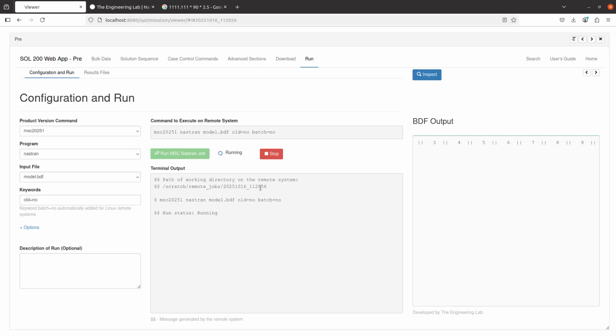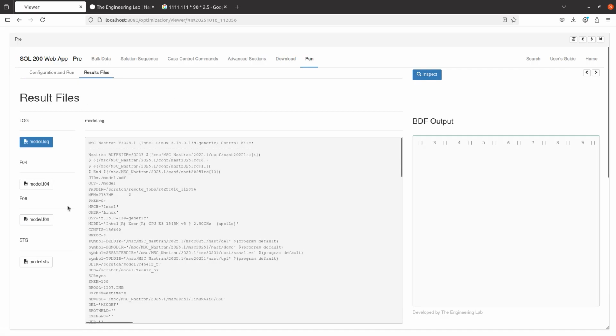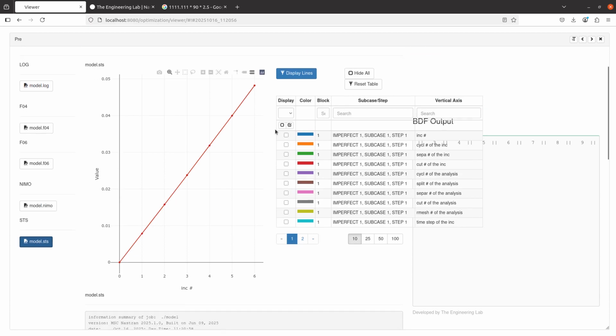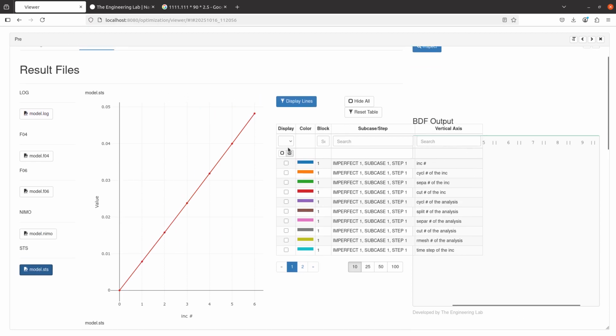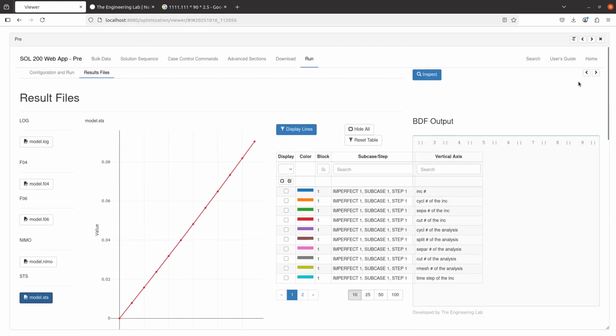So now this nonlinear buckling analysis is going to take a long time. One thing you want to keep an eye out for is the STS file. It's good to look at the displacement here, or the maximum response. Make sure that this maximum response is practical and reasonable.